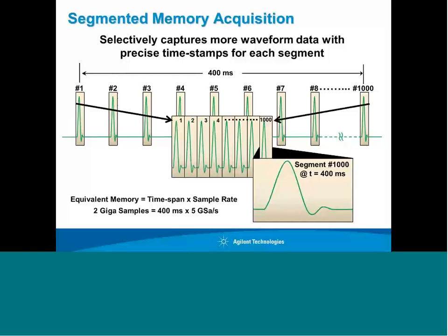Here we show the events with nothing in between. This could be a complex digital pulse stream, and we'll show a real example of that in a minute. You set up a trigger condition to capture just the event based on that condition, and ignore everything else.